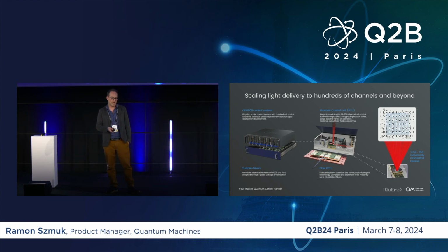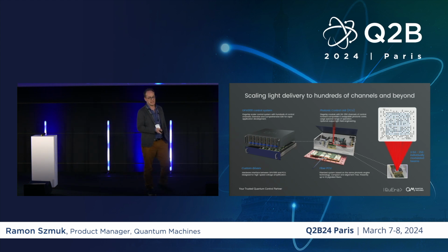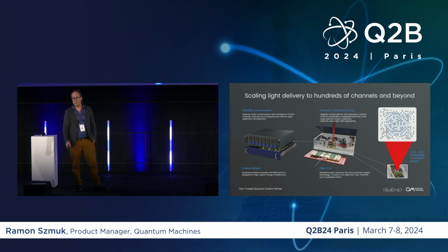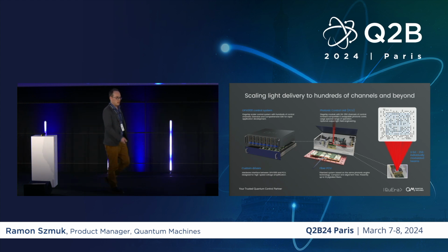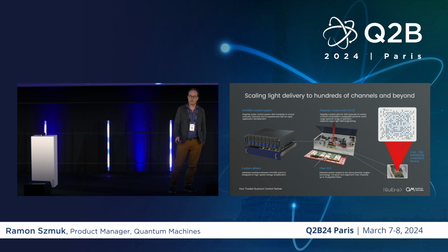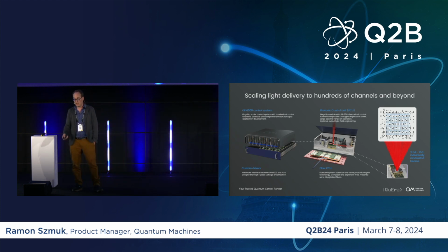1000. And so now we've basically extended the OPX 1000 from a few gigahertz up to hundreds of terahertz. You can think about this as an up converter. So you come in with a single fiber, it's split on chip, and out of the chip come 256 beams, which you can both steer in space, positioned on a 2D plane, and individually modulate with modulation bandwidths of 30 megahertz at least, and sufficient power.